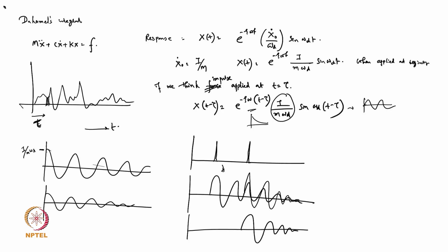And that is the fundamental of the Duhamel integral, and sometimes this is also known as the Green's function operator, because it is calculating at a particular point. We are solving the response for a particular time instant, and then we are integrating it over the domain so that we can get the complete response of the system. Make sense?